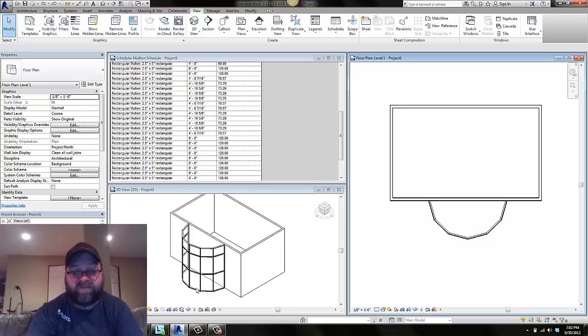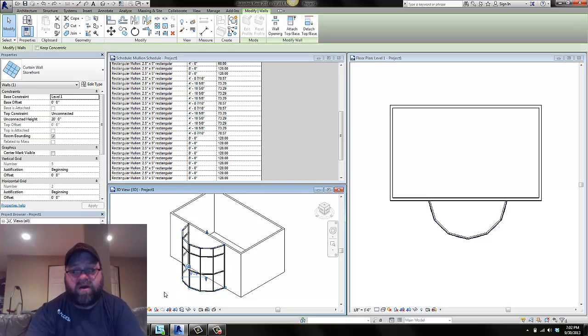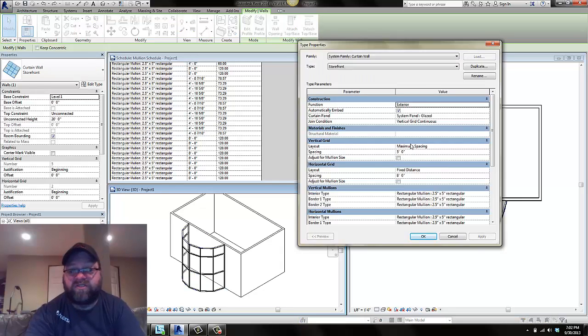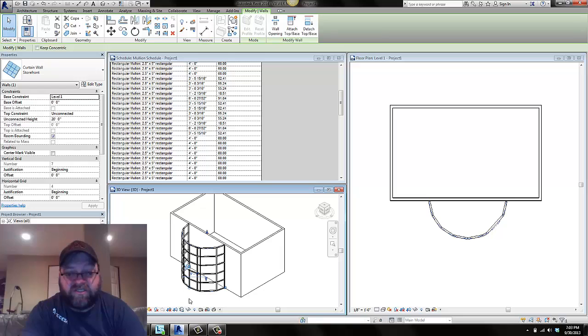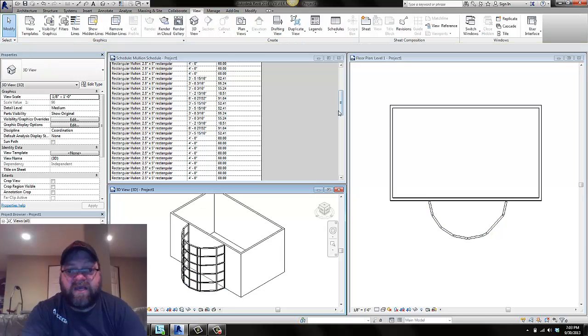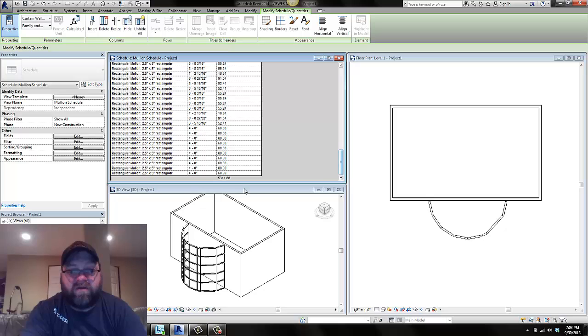So I can maybe look at something like, okay, now I know how much each mullion costs. What if I changed the spacing on these mullions? Instead of doing a 5x8 panel, what if I wanted that to be equal? What if aesthetically I wanted a 4x4 panel instead? Okay. And now I'll say okay to that. And so now it changes the look of this. And now I know that a 4x4 panel costs $5,000 instead of $3,800.